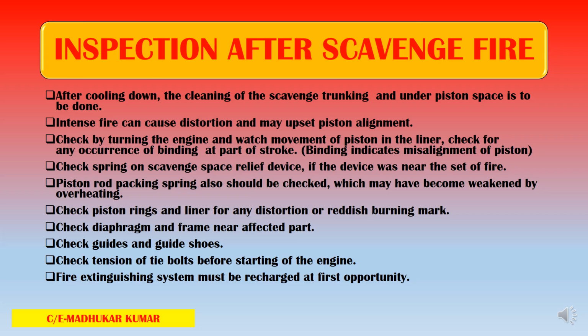Piston rings and liner condition must be inspected and checked for any distortion and any burning marks. If the steel has burnt, it can be easily identified, and it has to be checked. If the piston rings are not in a condition to be used now, they should be replaced.